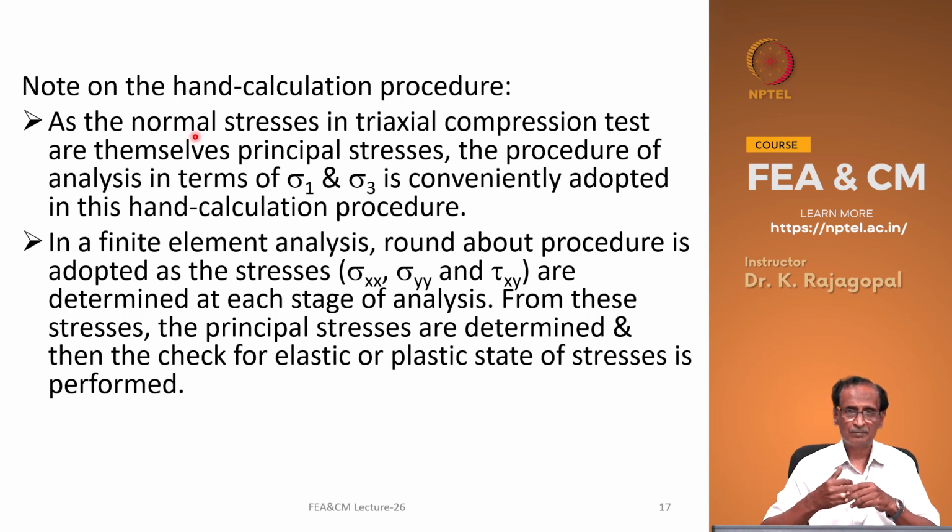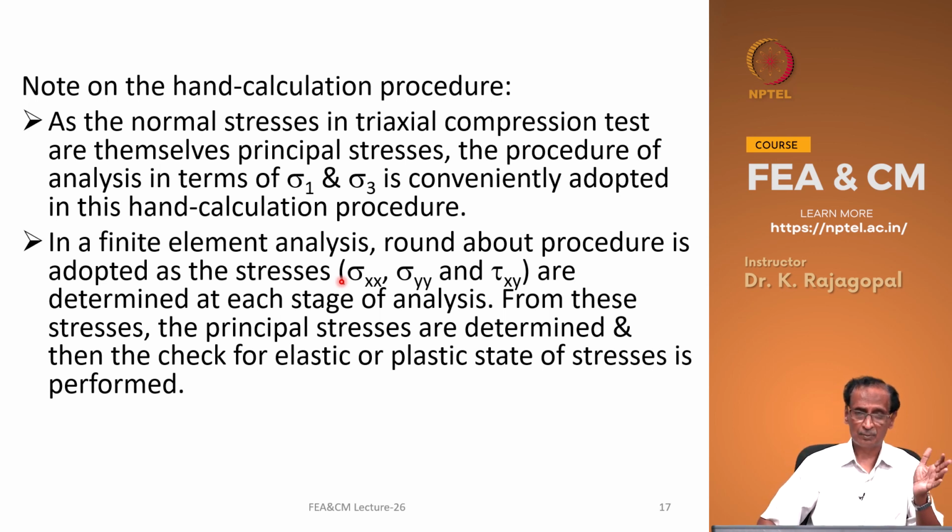But in a real finite element analysis, it is a very cumbersome process, because we solve first for the displacements, strains, stresses, and then the stresses are the Cartesian stresses sigma xx, sigma yy, and tau xy, and from these we need to estimate the principal stresses sigma 1 and sigma 3, and then check for the yield limit in terms of our sigma 1 and sigma 3, c and phi.